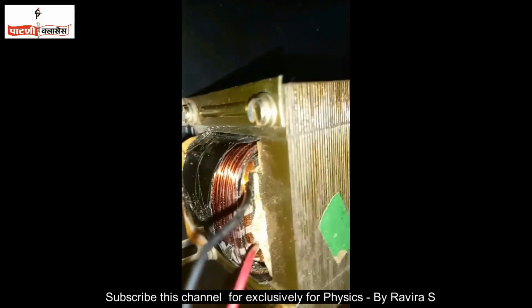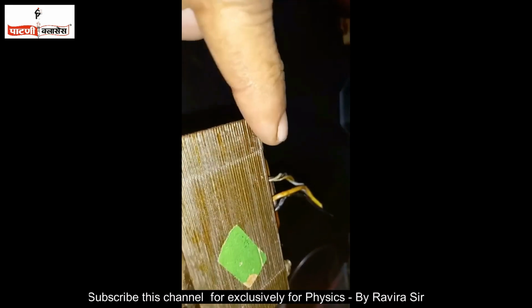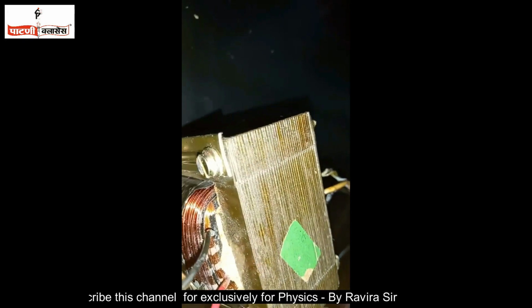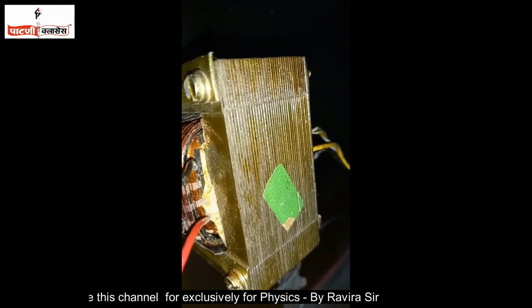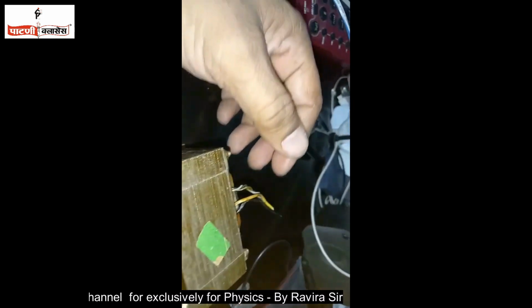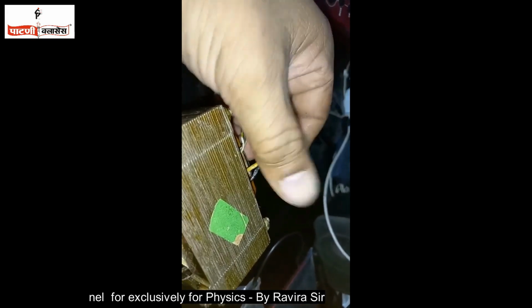This is a practical transformer, and these are the laminations. All are laminations. They are insulated from each other. For insulation purposes, generally we apply an oxide film or varnish. And here is the winding, and these are the two terminals taken out here, and here also a terminal for external connection.